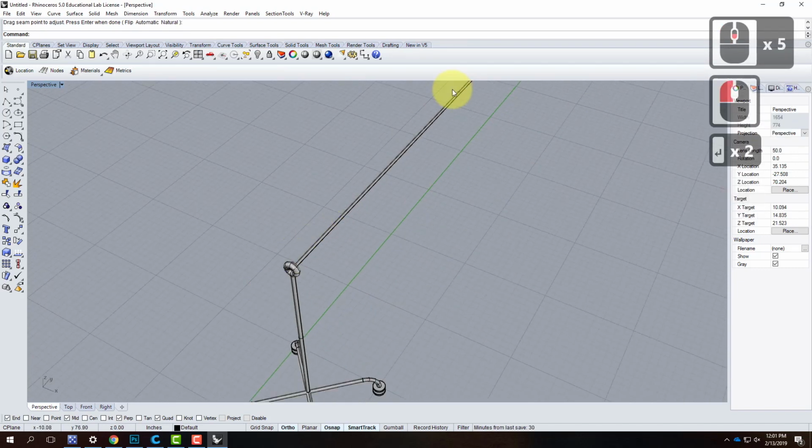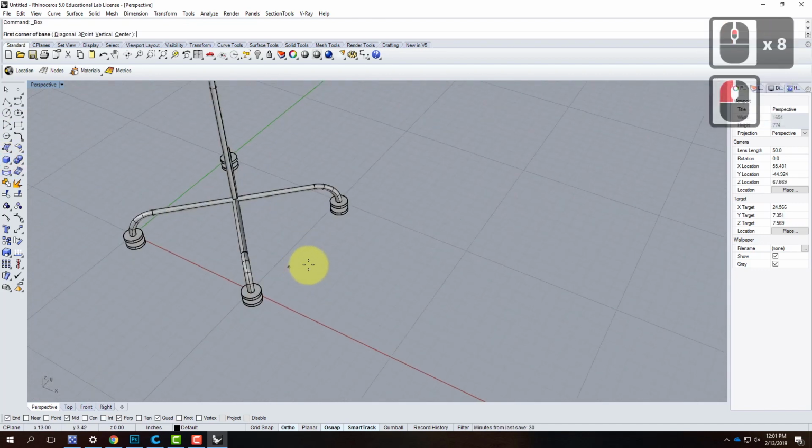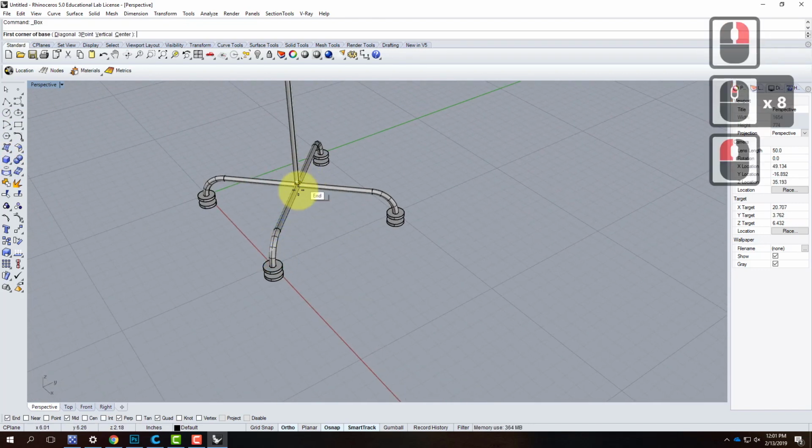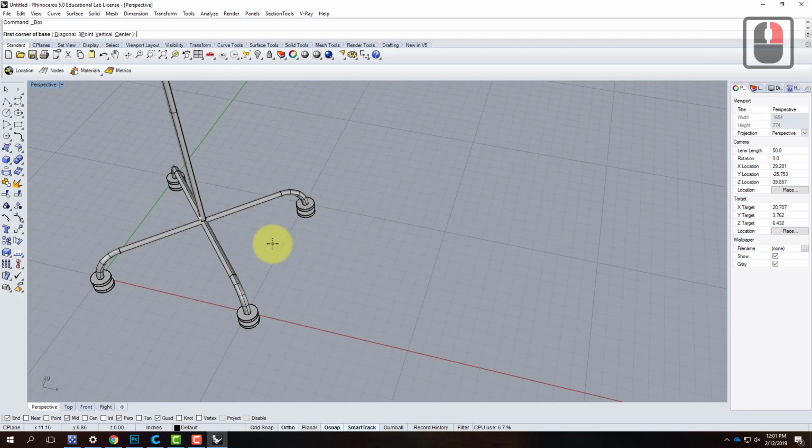Could I do this as a cylinder instead? Sure. Just another way of drawing it. So I've built this up, and that's good. Next thing I need is the piece of glass for behind this. So I'll go ahead and use my standard primitives. That'll work. But I'd like my piece of glass to start directly underneath this center, which happens to be at 6 inches by 6 inches. So I can go ahead and just type in 6, 6 as my starting point.